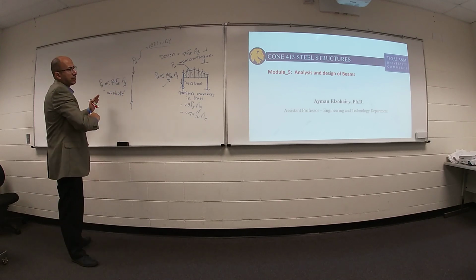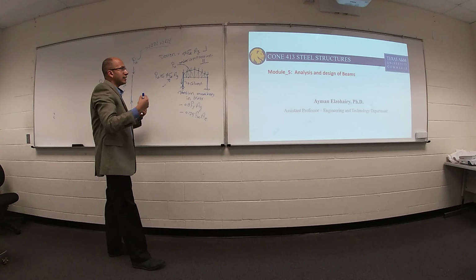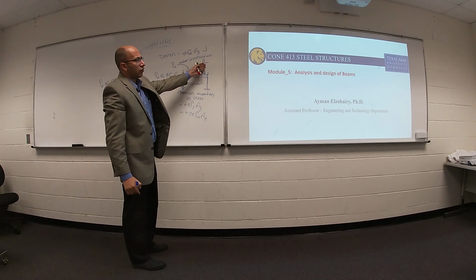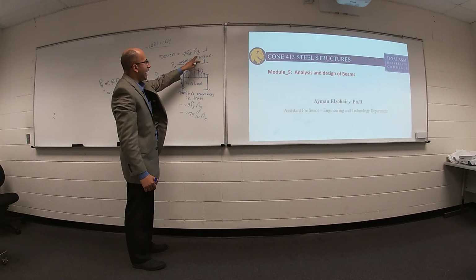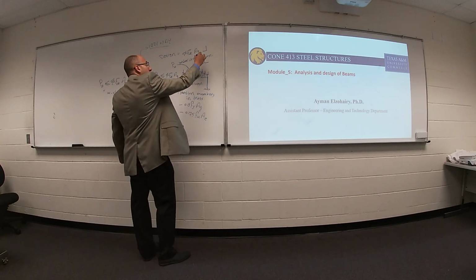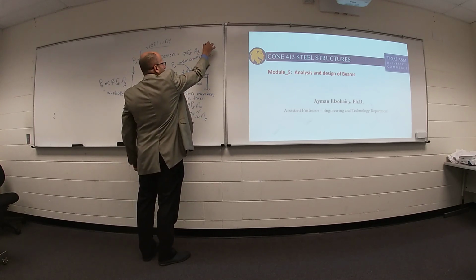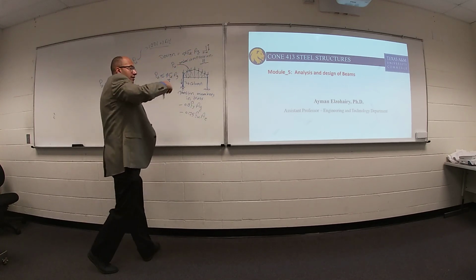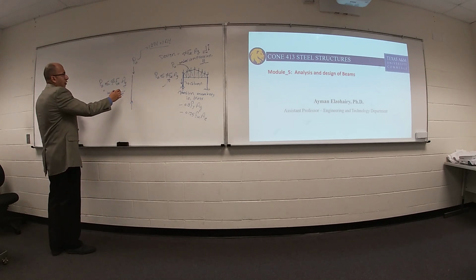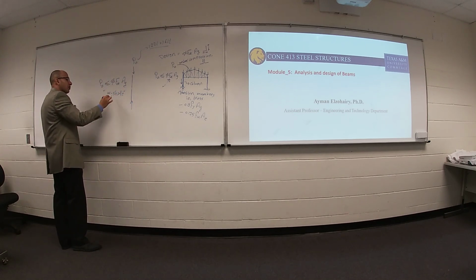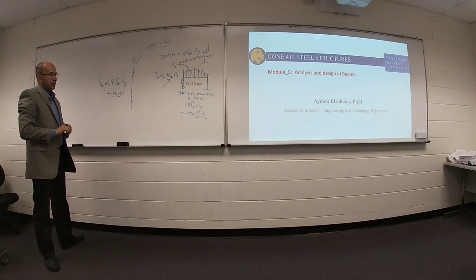The same steps in design, but we selected another type of cross section. For truss, we are using angle or double angle. Most of the time, equal length. 6 times 6, 8 times 8, 4 times 4. For column, we are using most of the time W shape.